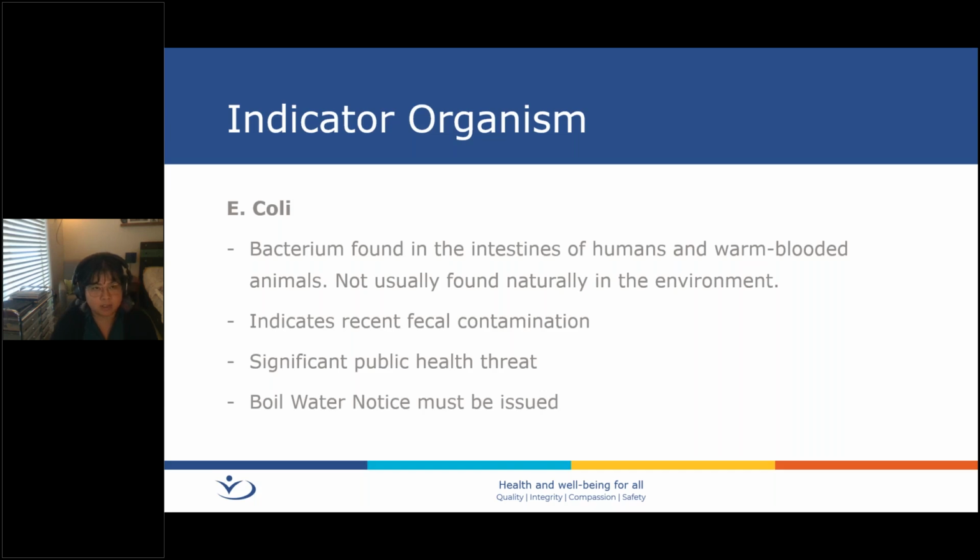So there is a greater risk that pathogens are present, so disease-causing microorganisms are present. And so when you're seeing fecal coliforms or E. coli in your drinking water, it does represent a significant public health threat, and a boil water notice must be issued in this situation.